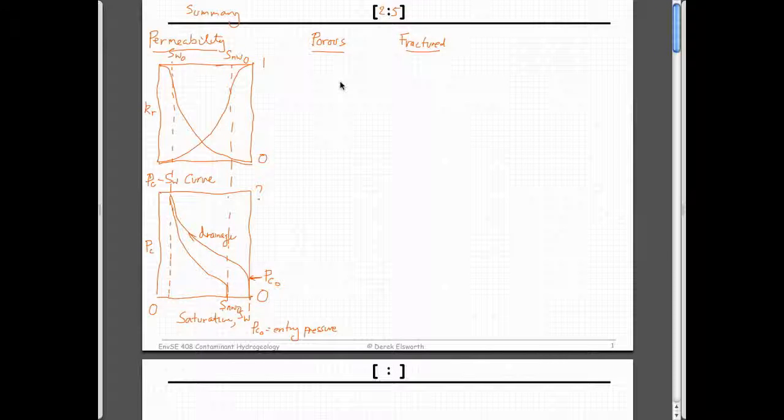If you remember the porous medium from last time, it looked like Swiss cheese with a whole bunch of different pore sizes in it. Each of these had some kind of diameter to it. And we derived last time that one approximation of the permeability is defined as the square of the pore diameter, the porosity of the porous medium, and some multiplier, 96 or 32. We derived that last time.